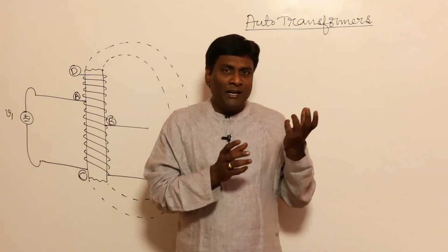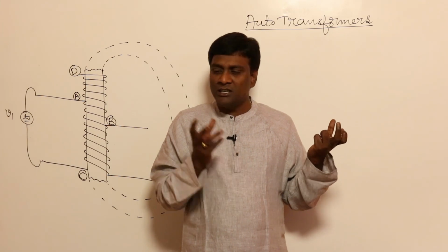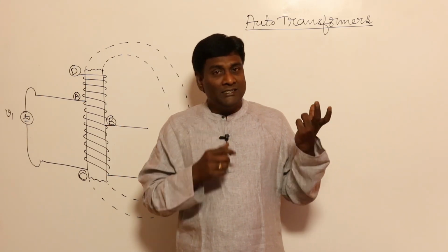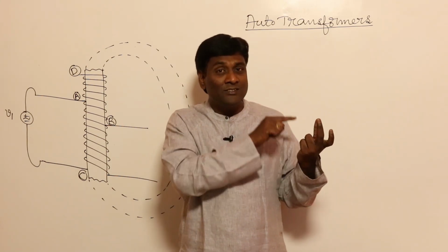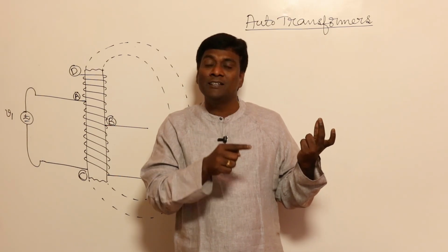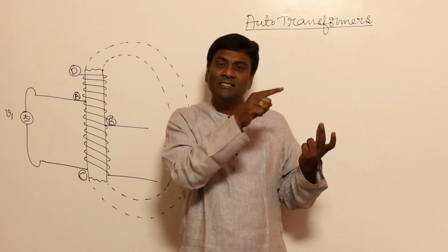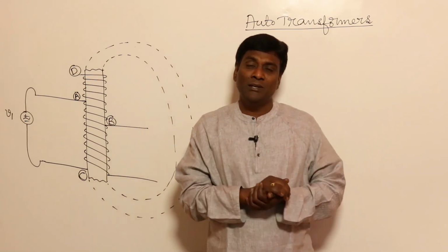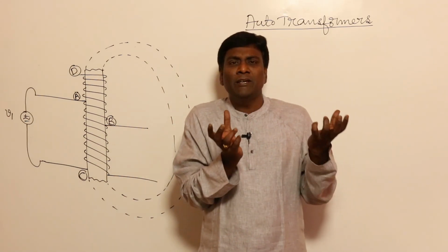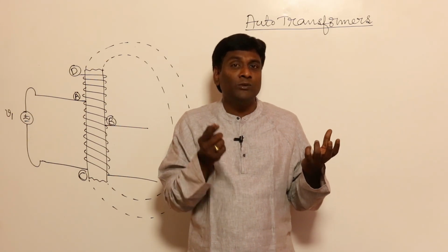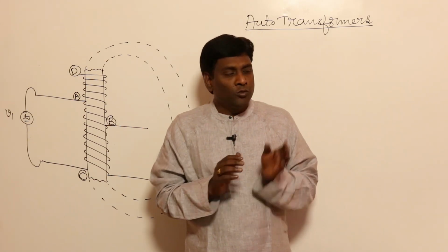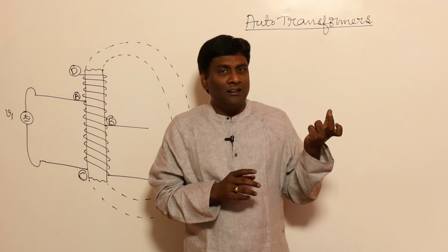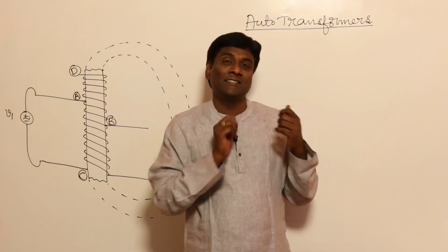Let us compare our normal machines lab rheostat and auto transformer. In our machines lab rheostat, the resistivity of the wire is going to be very high, such that resistance effect will be more, and inside we are not going to have any high relative permeability material like iron, so it's going to be air core, so relative permeability is less, so inductance effects are going to be less. So the moment inductance effects are less, we are going to model that with resistance only.